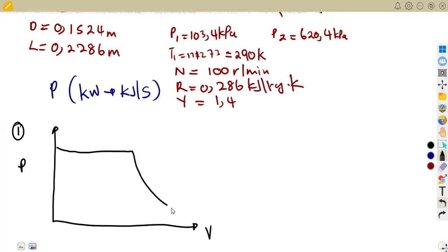So our PV diagram, as we saw in the previous case, is going to be like this. All right, so this is PV to the exponent of gamma, which is equal to a constant since it is adiabatic, where gamma is 1.4, and at the inlet we have 0.1, which corresponds with the V1, at this 0.2, and so forth, which is our V2, P2 here, and P1.